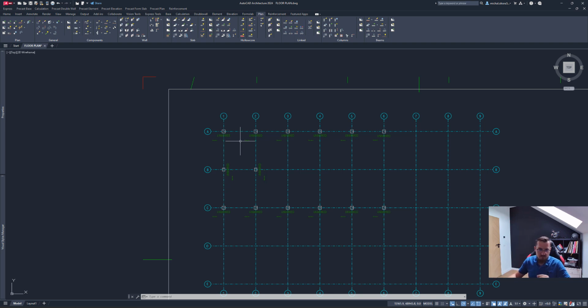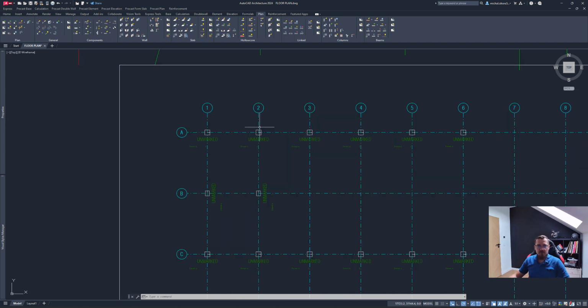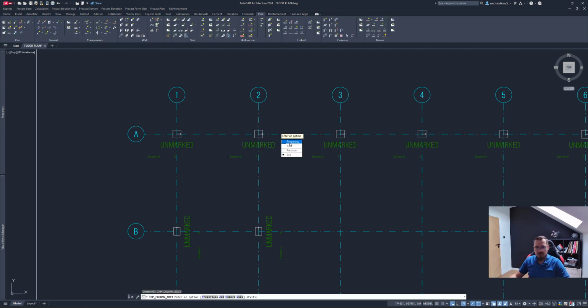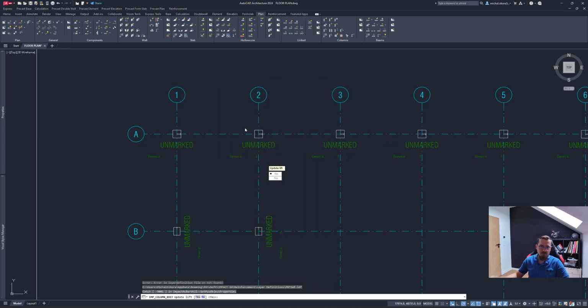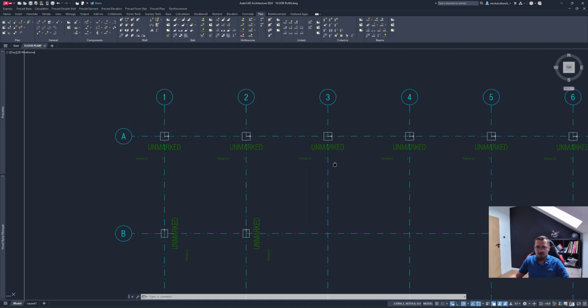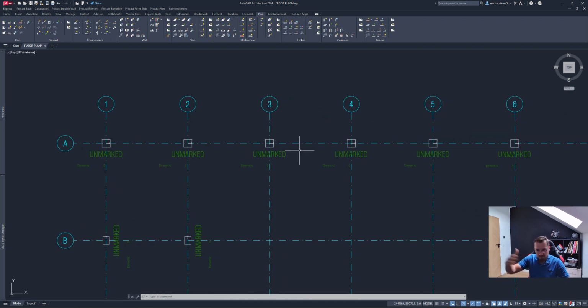What we can do now is play around with the reinforcement of those columns. So let's go back and open up one of the columns and go back to the properties, just to remind ourselves. There's a reinforcement, there's a template. This template gives us some insight into how the reinforcement will look. We won't be able to see 3-dimensionally how that reinforcement will look, as this is something that we, in Impact for AutoCAD, do at the drawing level. So we can apply a template, but then the reinforcement we will see only on the drawing. So not a problem there.